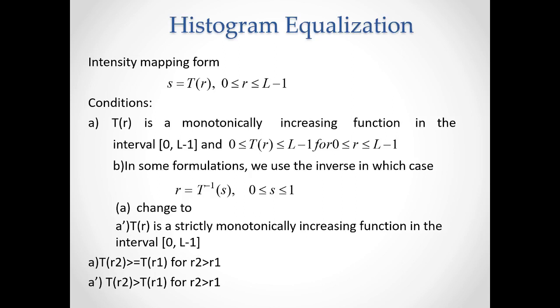Histograms are used for various image processing applications, like manipulating the contrast and brightness of a digital image. The histogram can control the quality of an image by normalizing the histogram values to a flat profile. So, to get a high quality image, the histogram values should be normalized to a flat profile, as you can see in this example.